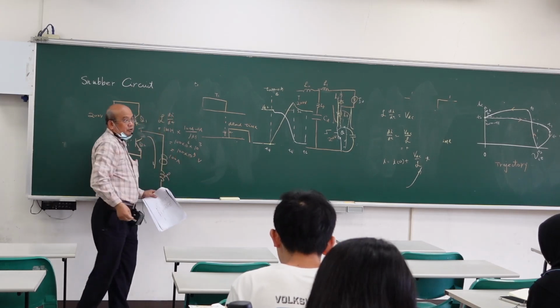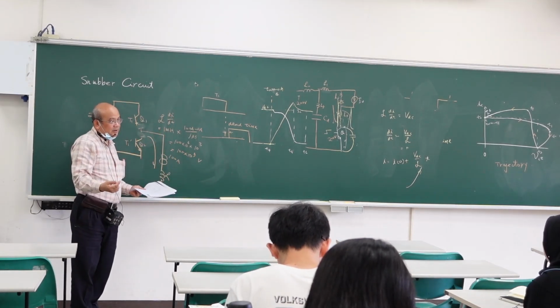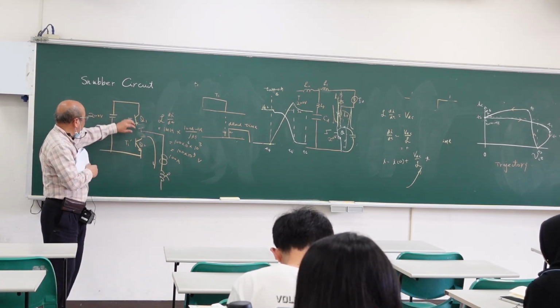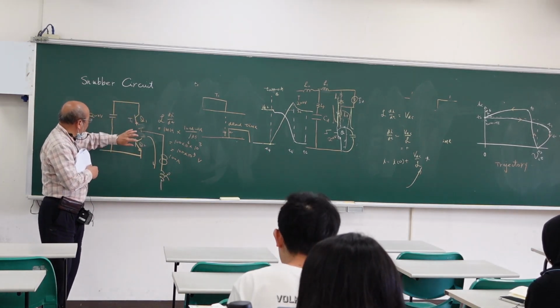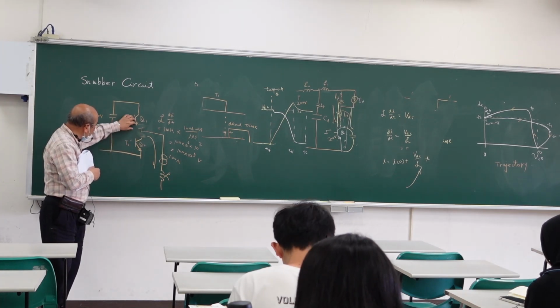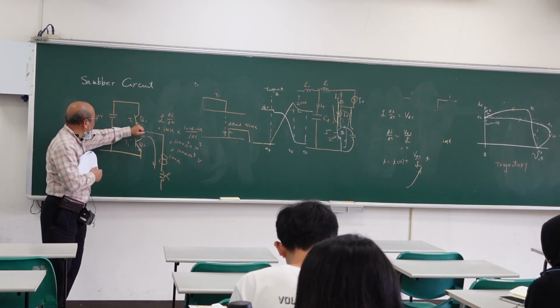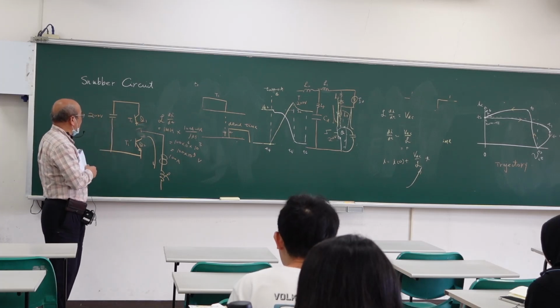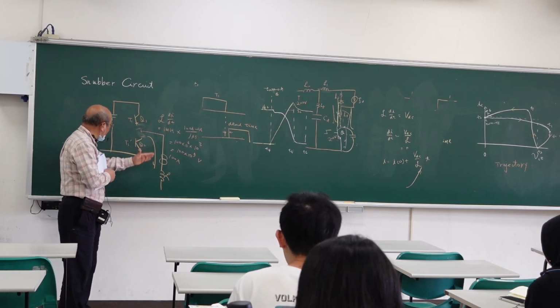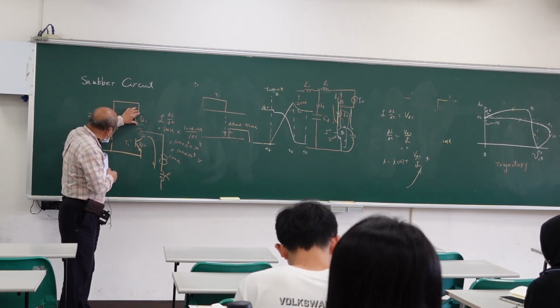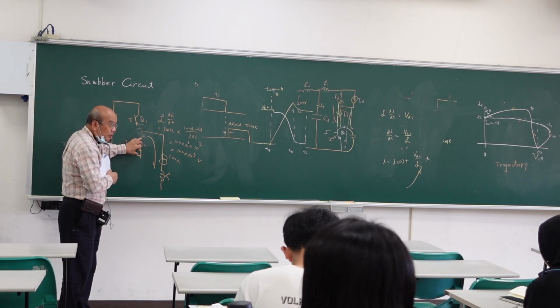this voltage. Then what happened? Damage everything, right? So you can see I cannot turn on Q1 and Q2 together. So after Q1 turns off, I just turn off Q1, but I have to wait during my waiting time. Then this is turned off, this is not turned on yet.